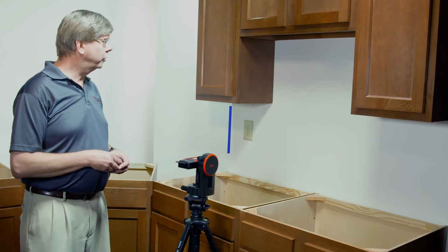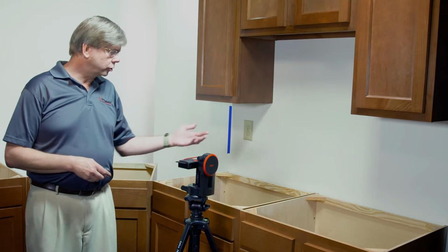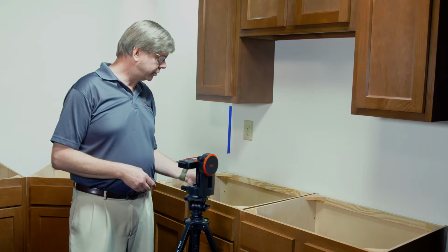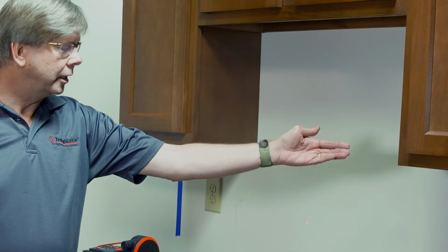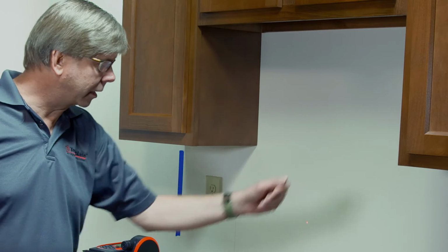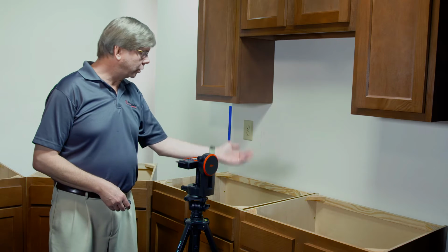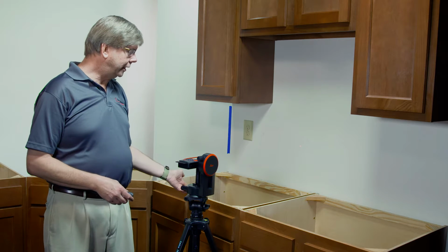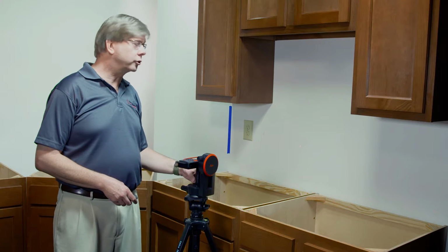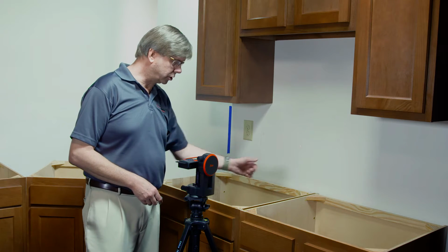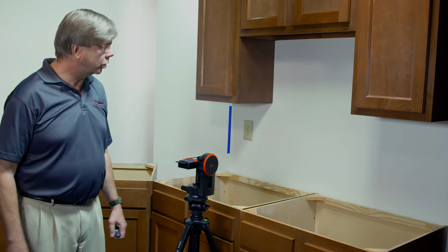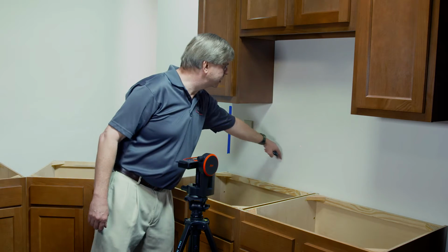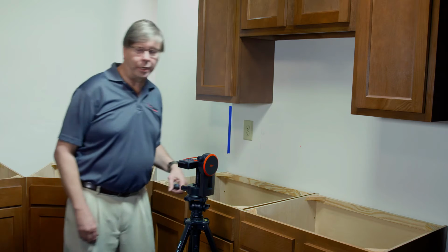Okay, we're back, and we're going to now do our full height splash. You'll notice in terms of the laser position, it's still on the tripod. It's about halfway between the top of the lowers and the bottom of the uppers, so that we'll be able to get all of our measurements. When needed, you can also take the laser off of the tripod, and it can be just laying by itself on a small foot. So right now we need to establish this back wall as our XY coordinate system.